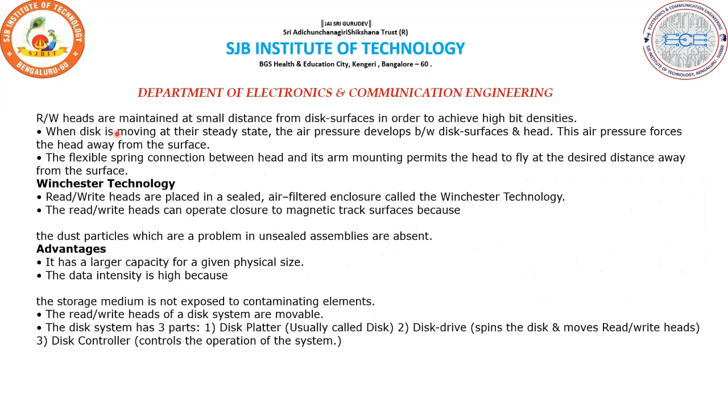So read or write heads are maintained at a small distance from the disk surface in order to achieve high bit densities. When the disk is moving at the steady state, air pressure develops between the disk surface and the head. This air pressure forces the head away from the surface. The flexible spring connection between the head and the arm mounting permits the head to fly at the desired distance away from the surface.